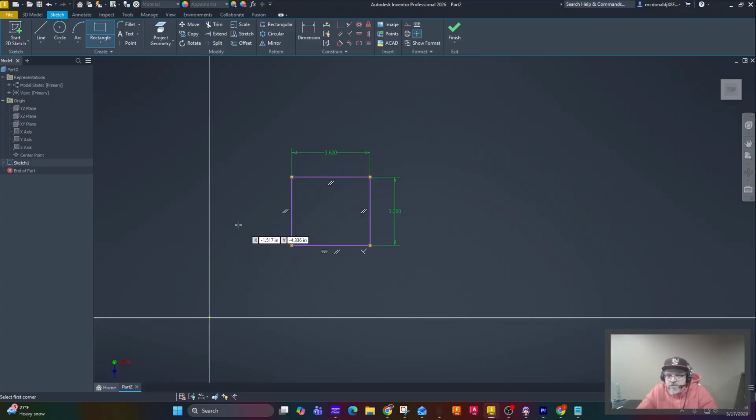It's really helpful when you've got sketches that are crossing each other or don't quite touch. One of the magic tricks that I like: you use the Coincident constraint, you click this bottom corner here, you click your origin dot, and the whole thing moves right on over. The whole thing is fully constrained, and you're good to go with the extrusion part now.